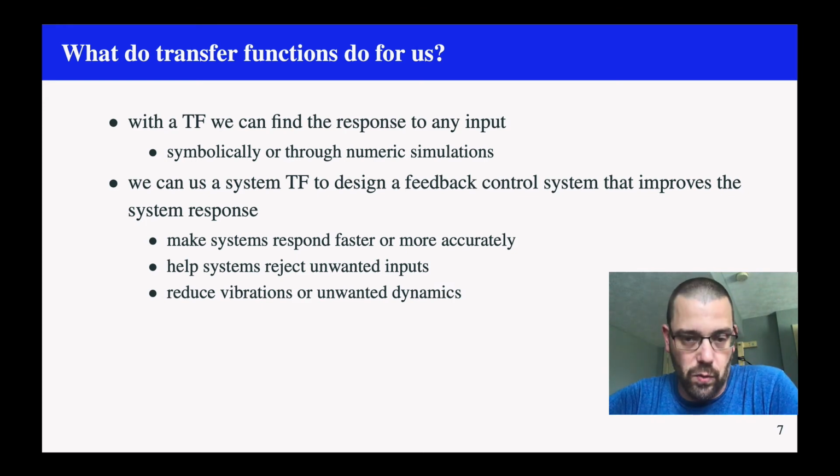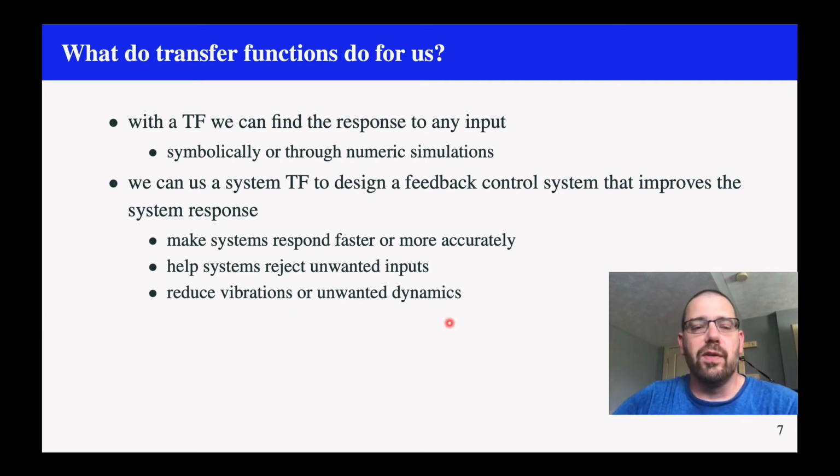Well, if I want a feedback control, I'm really best off if I can design that. And so if I want to design a feedback control system, then a transfer function helps me do that. And there's many tools, such as the root locus or Bode compensator design or whatever, as well as tools to simulate the closed loop response. So having a transfer function allows me to design a feedback control system that can help my system respond faster or reject unwanted inputs or reduce vibrations or otherwise eliminate unwanted dynamics. So it can do a lot of really powerful things for us.